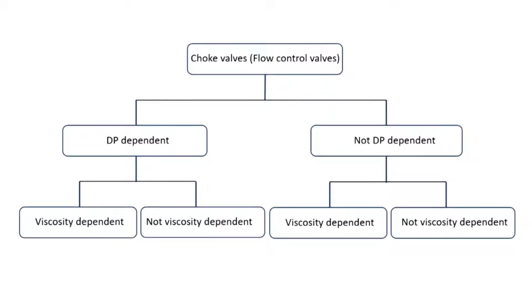In this video, I'd like to talk about choke valves. We use choke valves in order to regulate the speed at which liquid flows through the system. Flow rate is connected to speed and pressure is connected to forces within hydraulic systems, and so choke valves determine the speed at which hydraulic components operate.